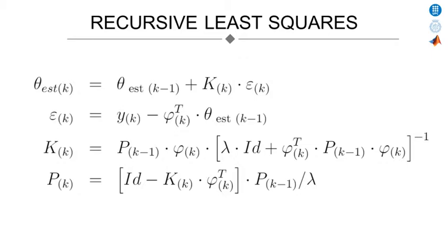This last one is obtained by subtracting from the actual output the regression model built with the parameters estimated on the stage before. Lambda, or the forgetting factor, has a very high influence when estimating the parameters. The higher the parameter, the smoother the parameter estimation, since k goes to 0. When lambda is less than 1, the estimator gain k will not go to 0 and the estimates will fluctuate. These fluctuations increase when decreasing the forgetting factor. That's why the best option is to choose lambda equal to 1.